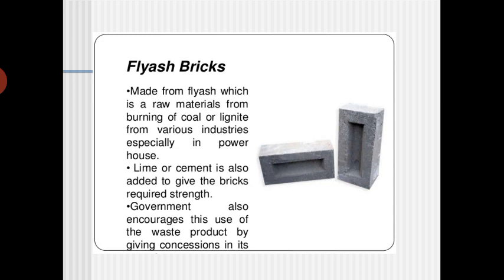Lime or cement is also added to the bricks to acquire strength, sometimes if you want a better strength. Normally what we do is mix the fly ash, lime and cement. Of course, the very important thing is that the major composition of the lime, of the fly ash and of the cement are very important aspects when you are considering the design of these bricks.